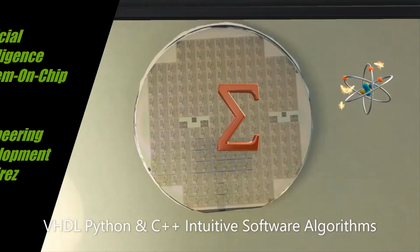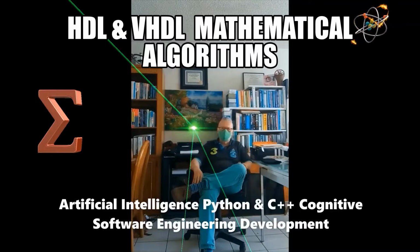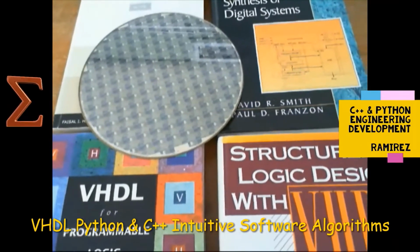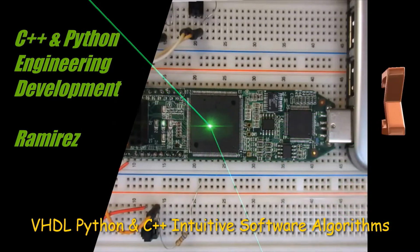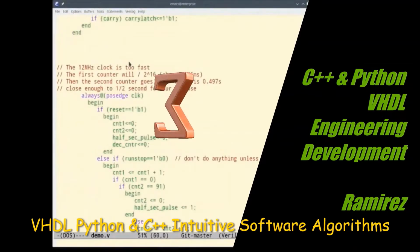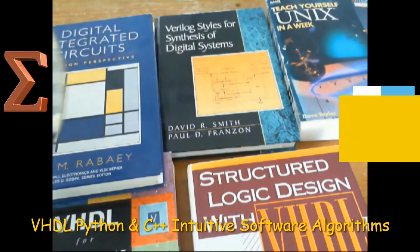One wafer produced 20 dies, of which 17 passed testing. The yield of good dies in this case was 17 over 20, which is approximately 85%. These good dies are then bonded into packages and tested one more time.